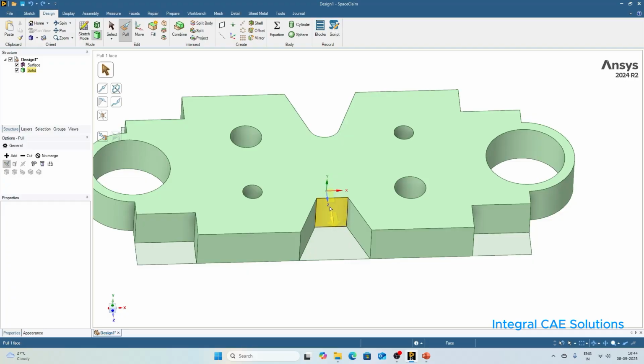Now what if we want to move this surface straight into the material without changing its size, or without this quadrilateral reducing its size? You can do this by selecting this surface and the connecting edges at the same time. Once we select this surface and the two adjacent edges, we can pull this in the direction. You can now see that the angle constraint is bypassed and the size of the rectangle is the same during the pull operation.